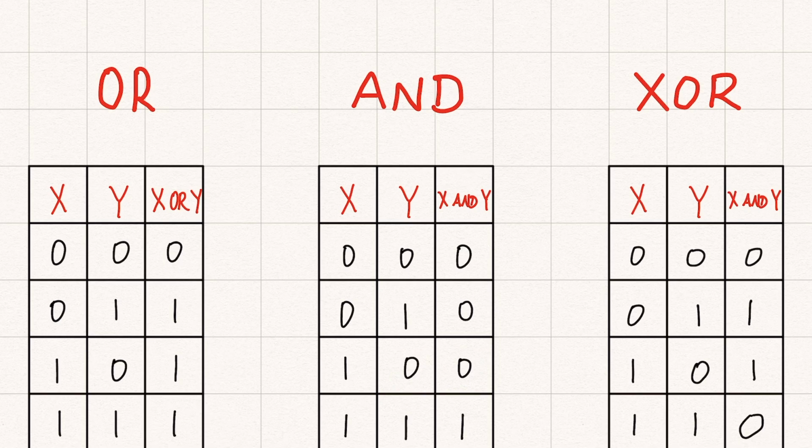Now the exclusive OR operator has something really nice that we should notice. If we have a value of 1 in the exclusive OR, as in this case, then if we exclusively OR a 1 with this 0, we get a 1. And if we exclusively OR a 1 with a 1, we get a 0. What seems to be happening is when we exclusively OR a value with a 1, it will flip that value. It will toggle it, so to speak. So here we have a 1. If I want to exclusively OR a 0 with it, then the 0 will be toggled to a 1. Likewise, a 1 will be toggled to a 0.